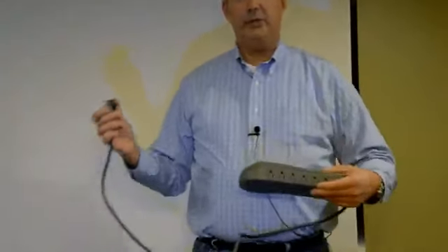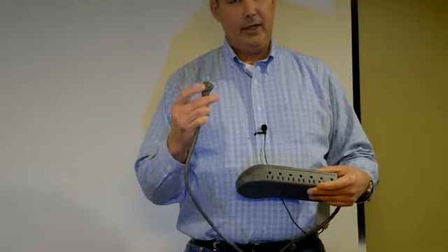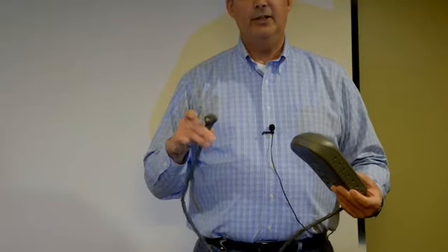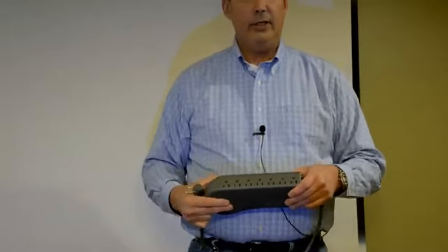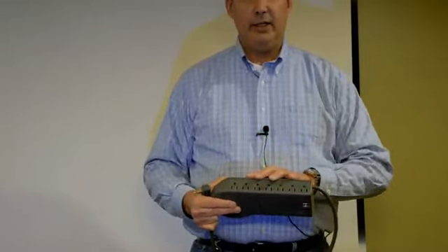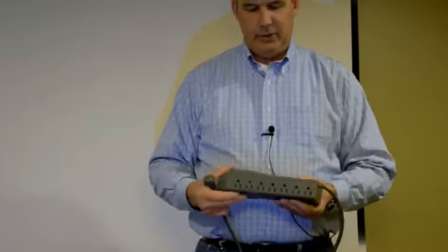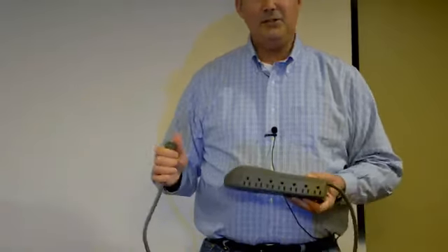and it does have surge protection, and it has a ground lug. Again, grounding is super important. Surge protectors don't work without proper grounding. So you can't have a surge protector and just a 2-prong plug. You have to have a 3-prong plug. Very important. Also, these surge protectors vary in the amount of protection that they have. They also have indication. Surge protectors in this form come in all sizes and shapes.